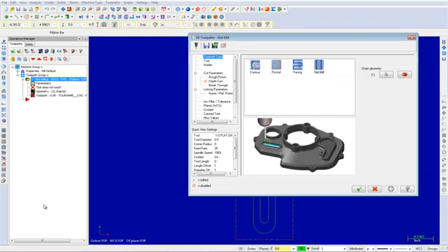Now in the toolpath type page, choose the slot mill icon. Mastercam updates these pages as you modify them and then marks them in the tree view list with a green check mark. Pages that are not changed are marked with a red circle and slash. We will now choose the 1/8 flat end mill and set the tool parameters. To do this, select Tool from the tree view list as shown.